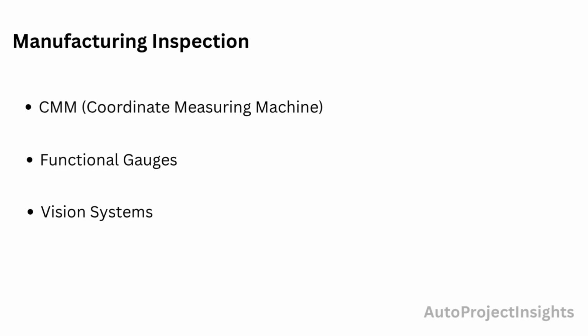No matter which method is used, the goal is the same: to verify that the center of every hole remains within the specified position tolerance zone. If the hole center is inside the tolerance zone, the part passes inspection. If it is outside the tolerance zone, the part fails because it may cause assembly problems. That's how manufacturers ensure every steering column bracket fits perfectly in the vehicle.